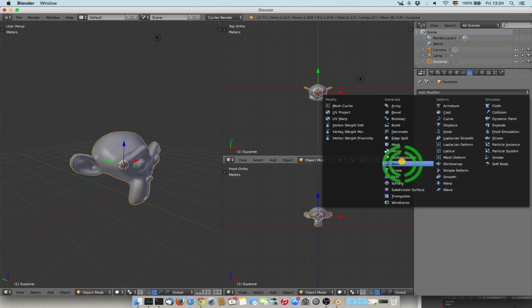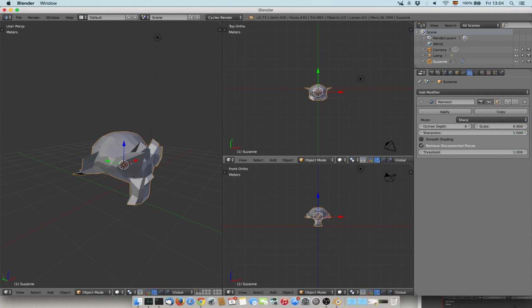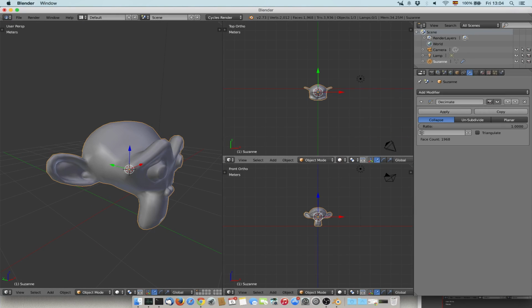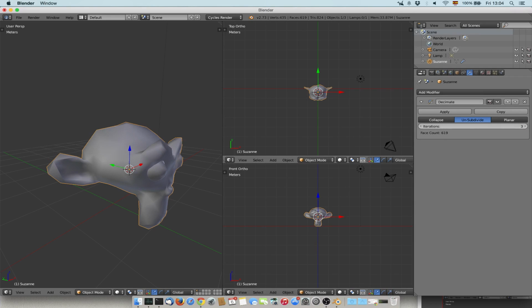The other one, I think, is Remesh. Remesh will start from scratch, so you can do this and then you select the thing that you want to get. This is rebuilding from scratch, so you don't necessarily get what you need, but it's a good way. Decimate depends on, for example, this is with subdivide. It's basically the undo of the surface. Okay, so you can change the way it works.